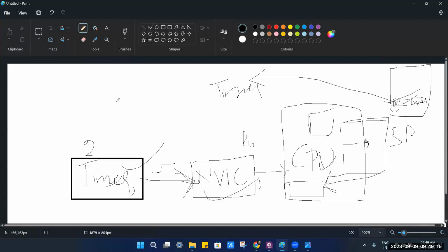There is always a confusion for me, which is supervisor and which is ordinary. Which is it in case of ARM, is thread mode supervisor or handler mode supervisor? See, we will discuss about this, but one more thing, what you are saying now, thumb and this architecture. That is one thumb instruction and ARM instruction. The ARM instruction set was now removed. Now it is all thumb only. It is a condensed architecture, thumb 2, which is a combination of both. But it is a condensed architecture, and that old ARM 32 architecture has been obsolete. It is deprecated now, from what I understand.